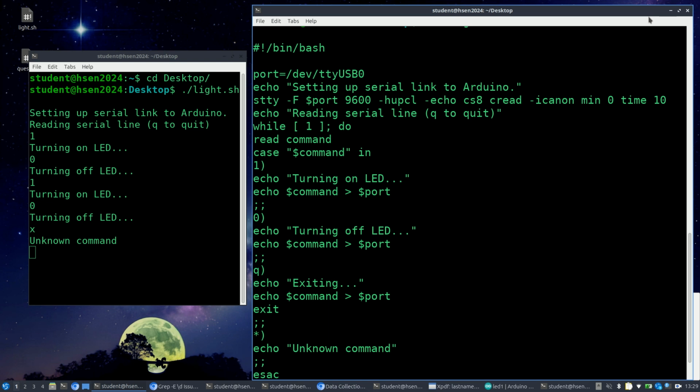Okay. The LDR is the light-dependent resistor. It's the one that looks like this. It's got legs like this, and it's got this little octagonal thing that looks like a snaky thing on the top. Okay, that's the sensor. That's the light-dependent resistor, where the resistance varies depending on how much light you're shining on the top of it. It's kind of a pale brown color on top with the two legs sticking straight down. The other one is the thermistor. The thermistor is orange, and it has a silver band across it.